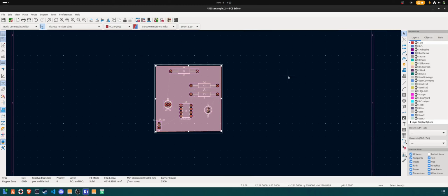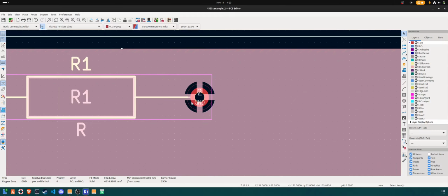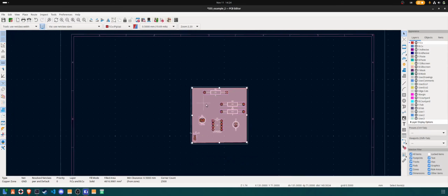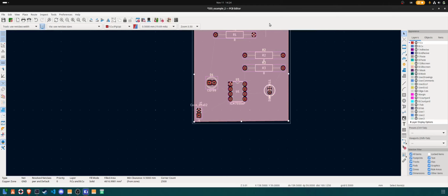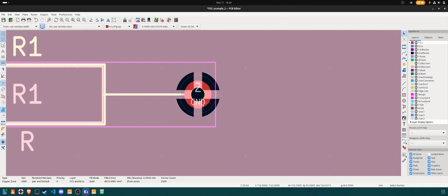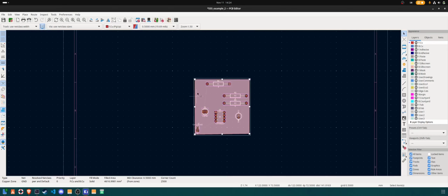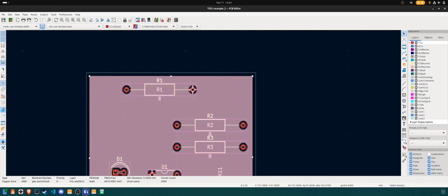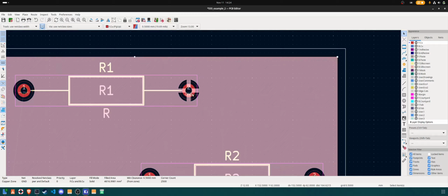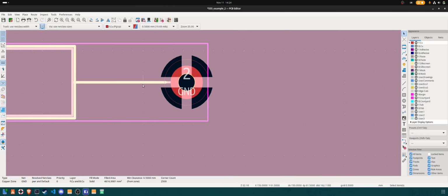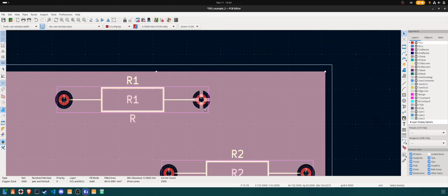And so now we have both of our planes selected, and you can click over here on our layers to verify that they're both there. And this is what I was talking about, how they tie off of the ground plane. So now instead of running a trace from this connector up here to our passive, now it just ties into the plane, and this is all just copper. So before, this copper would have gone just unused and sat in the board, but now we're utilizing this ground plane to minimize impedances, and we have 4 solid connections on all of our components.